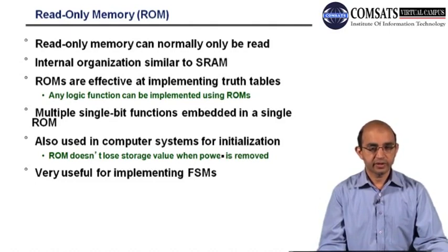In the combinational logic, whenever we talk about combinational design and combinational analysis, we discussed how we can move from circuitry to the Boolean function, and then from the Boolean function to the truth table. As we know, the truth table is a unique representation of any Boolean function.